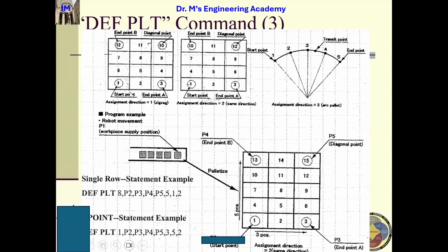left bottom. Keep in mind, guys. When you define the palette, you need to follow this convention. The left bottom is the first point, and the right bottom is the second point, and the left top is the third point, and the right top is the fourth point.